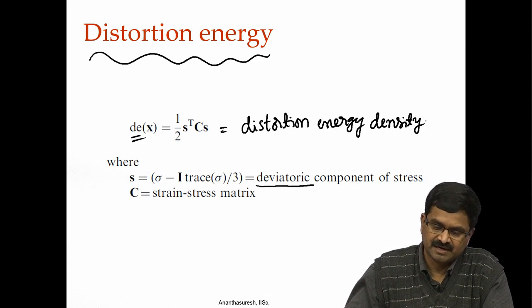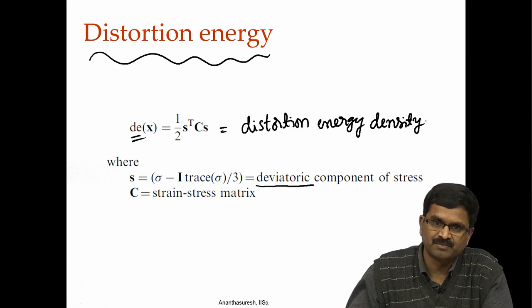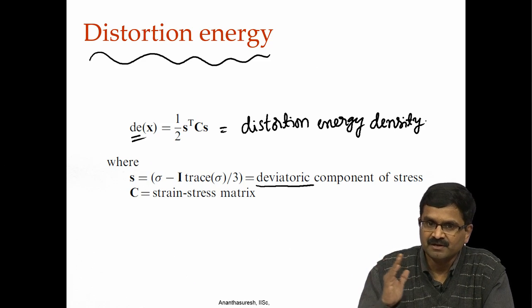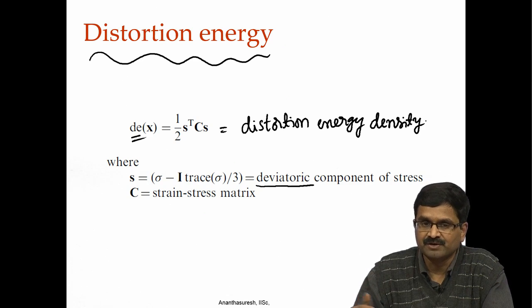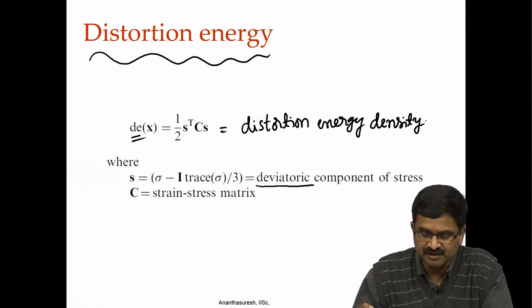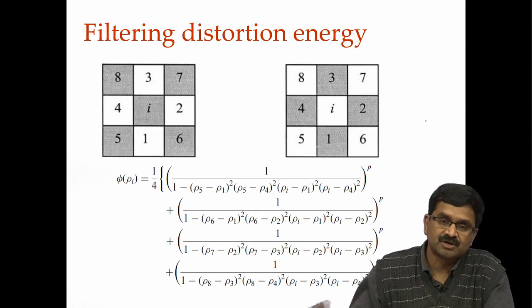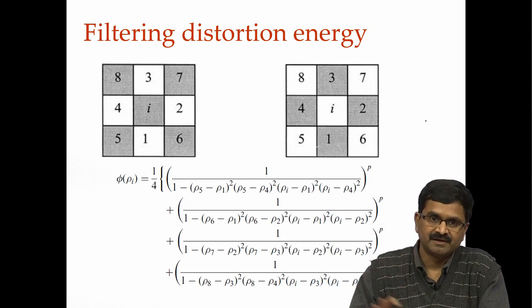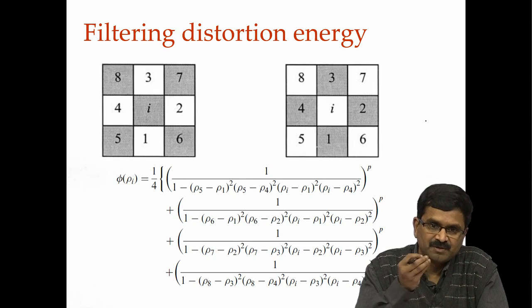ductile materials, right. So, we do not make compliant ways of brittle materials, although we could, and we do use silicon for example, a brittle material, but we have to limit our range of motion. Our design should be appropriate, not for it to just break with brittle material. If you see ductile materials, then distortion energy becomes important, and this distortion energy will be there in the continuum when you are doing this, but we know in topology optimization some elements will be disappearing, some elements will be present. How do you know where to apply this?